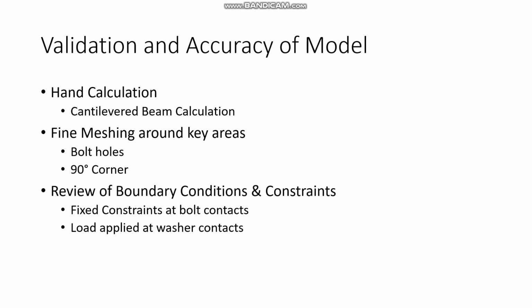To ensure a more in-depth analysis for the L bracket, hand calculations will be used to determine the maximum stress in the L bracket, which will be compared to the FEA model for validation. For a more accurate model, a finer mesh will be used around the key areas of the bracket, like the bolt holes and the 90-degree corner.